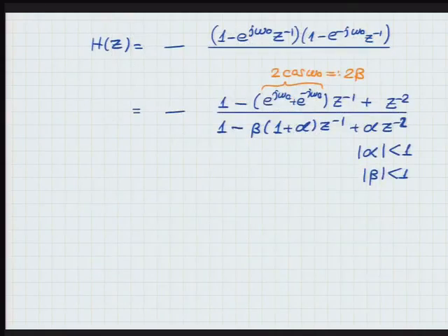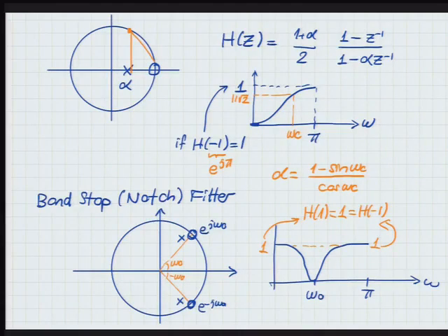This particular parameterization of H is in a form that you can make H equal to 1 both at z equal to 1 and z equal to negative 1. Right? That's one of the reasons why the denominator appears in this funny form with 1 plus alpha, alpha and all that. So it's adjusted so that, with your choice of alpha, you can actually set both of the coefficients equal to 1. Okay? All right, I'm not sure if that was clear. So the reason that the denominator is written in this form, with this 1 plus alpha, alpha here, etc., is so that when you look at the frequency response, you go back to where you were at 0 frequency at the high frequency. Okay, so there's no discrepancy between those, right?